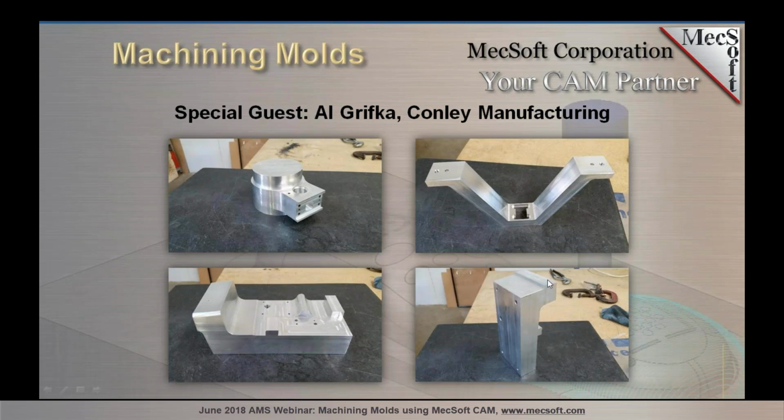It actually wraps around the other side here, and then here they would use a feeler gauge to check part tolerance. Same thing right here on this top part. These here would be the nets or the datums where the part would actually sit. And then same concept here, they would use a feeler gauge to check the contour of the part.